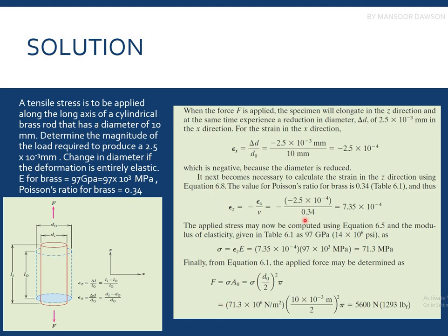So now we can calculate the stress basically. So we know that the stress is equal to the strain into the elastic modulus. So we'll multiply this value and the modulus of elasticity, which we got from the chart from the previous slide, and we get this value. This would be in megapascals because the elastic modulus is in megapascals and the strain is dimensionless.